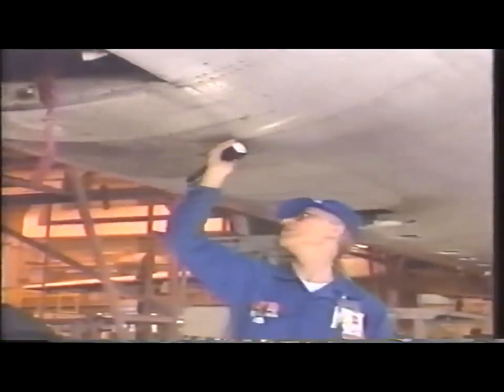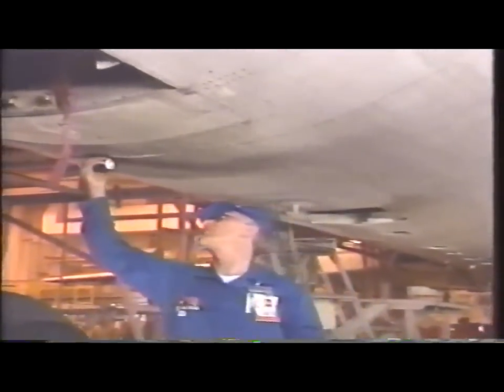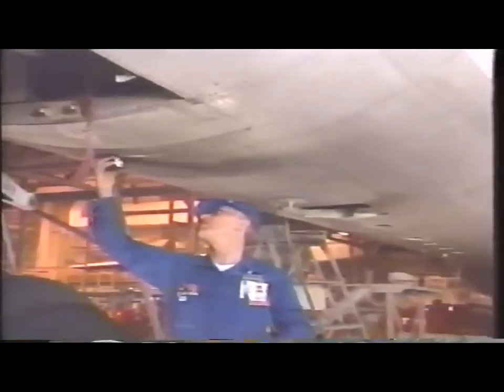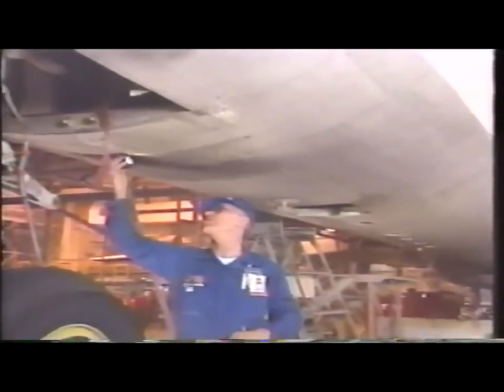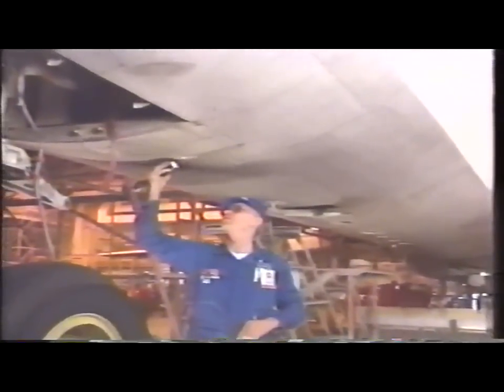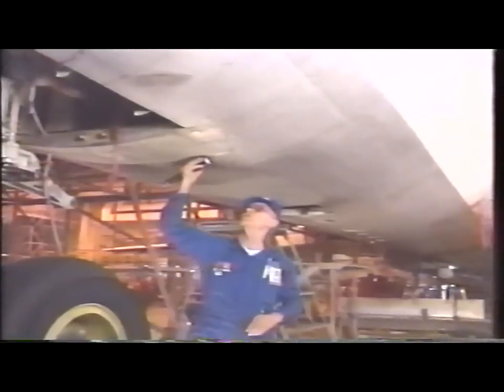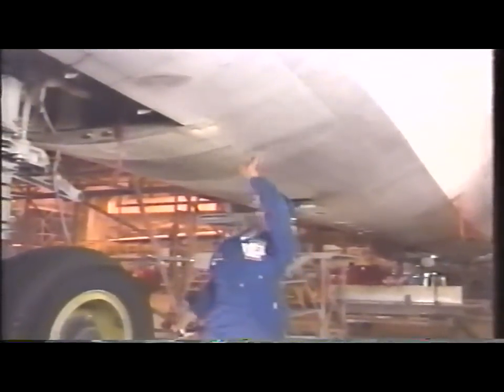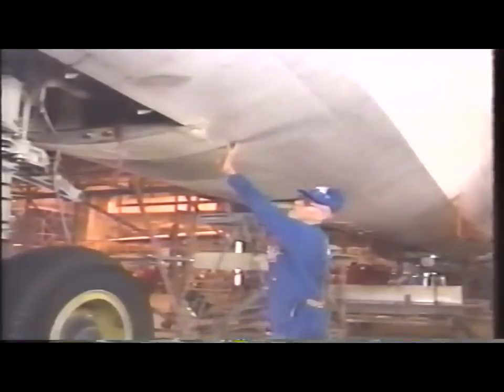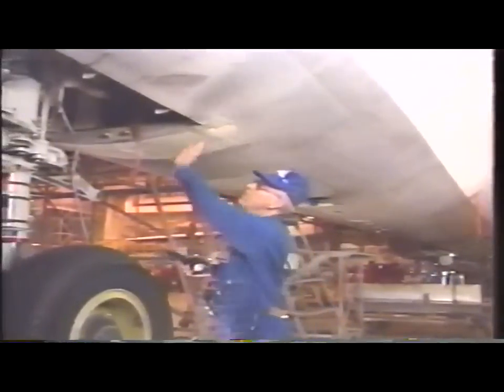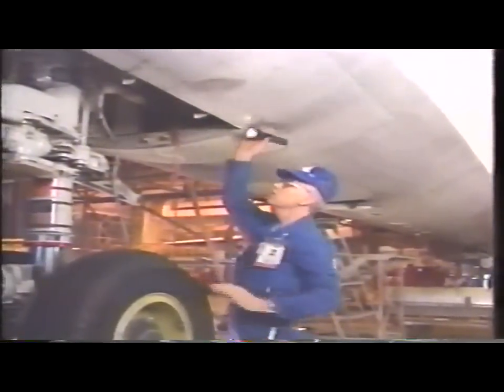With visual inspection, as the name implies, you use your eyes to detect damage on a surface which could indicate corrosion. By shining a flashlight at a low angle across the surface you are inspecting, any irregularities will produce shadows. This makes your job considerably easier. Additionally, feeling the surface with your hand can also help you detect corrosion. Visual inspection is the most widely used corrosion detection technique.